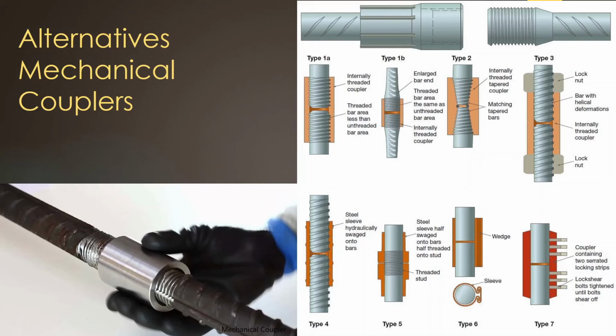In addition, you can do the staggering of the reinforcement laps. You can stagger the couplers and lapping, and also you can mix them so that the congestion can be reduced. There are different methods to use the couplers.